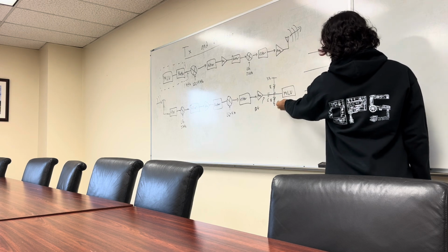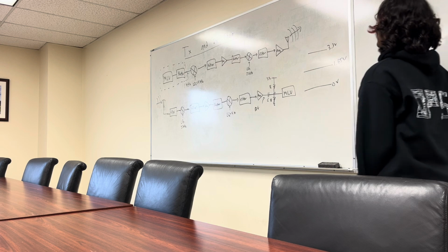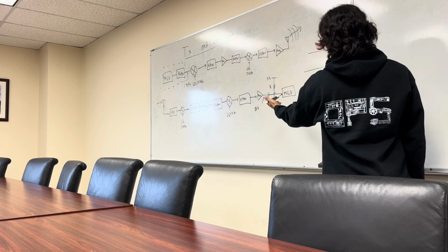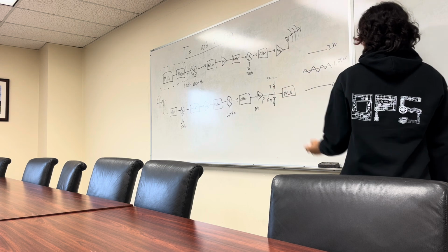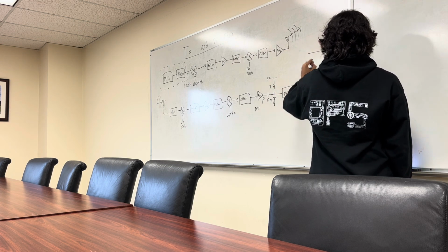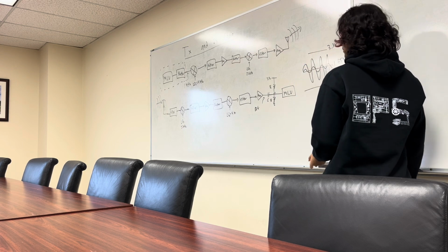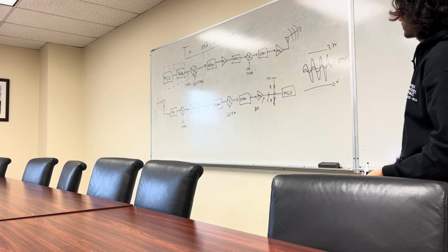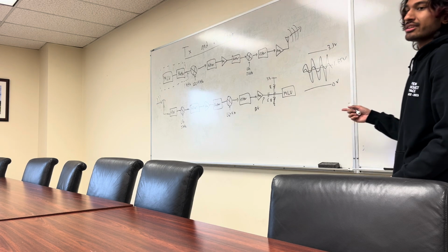And if these are the same resistor values, then you get 1.65 at that node, right? So now, if we have a signal coming in, it can be a small signal. We can choose to amplify it further, and we still maintain our dynamic range, right? So that's important. Any questions on that?